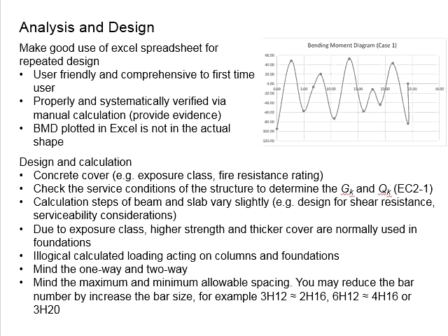However, for the slab, it is more concerned with the maximum spacing between the reinforcement bars. As the spaces are plenty, it is not normal to have reinforcement bars quite closely spaced, and the maximum spacing will allow the control of the cracking on the surface of the slab. Next, you need to consider the exposure class, where most likely you are going to expect higher strength and thicker cover for the foundations. We mentioned this.